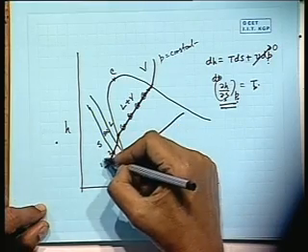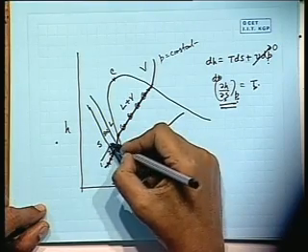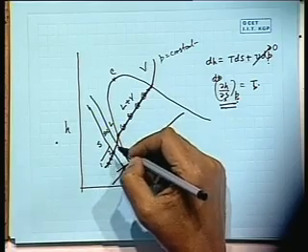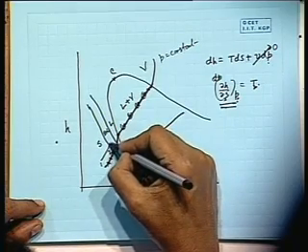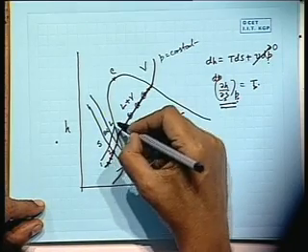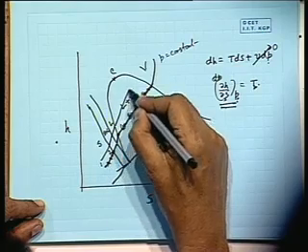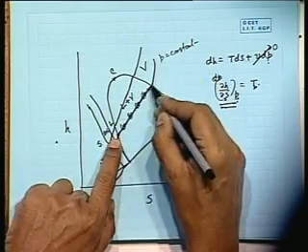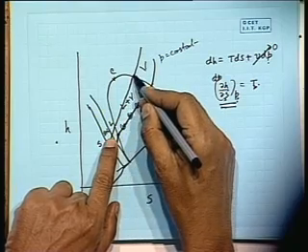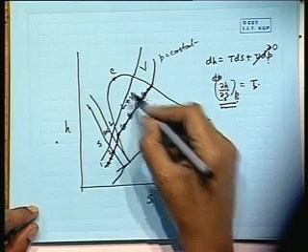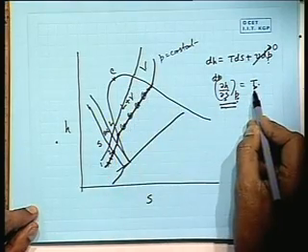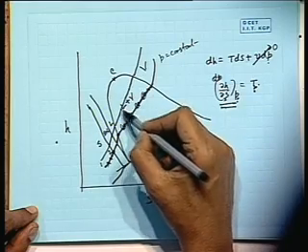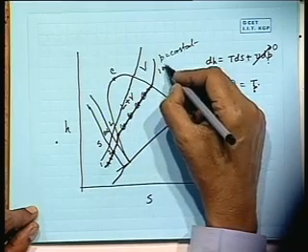And if you draw another constant pressure curve at a higher pressure, then this curve will have a greater slope. That means if you show this linear curve in the phase change region, don't draw it parallel to this. It is diverging in type, because the slope of this curve is more than that, since this is equal to temperature. So the saturation temperature is more than this. For example, this is the 1 atmosphere curve.